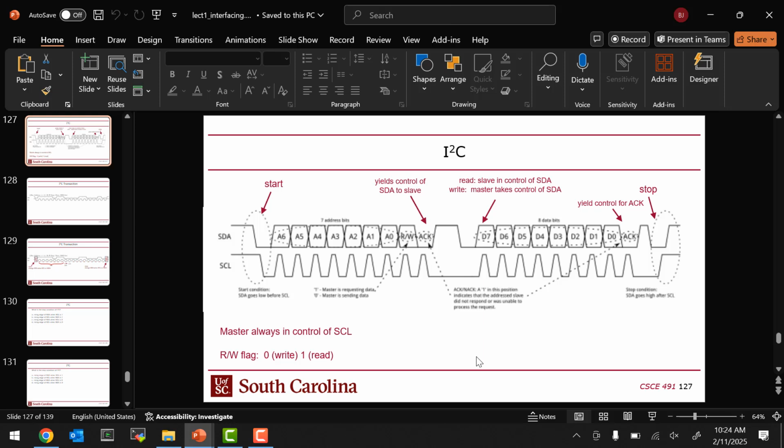The problem with I2C is that it's meant to have multiple slaves, and you can obviously have multiple masters. The presumption is that you have a whole bunch of things attached to it. Now in this lab, we don't; we just have the one sensor.